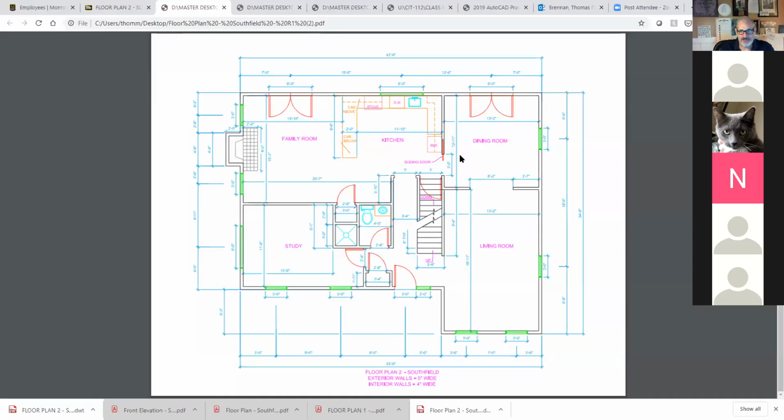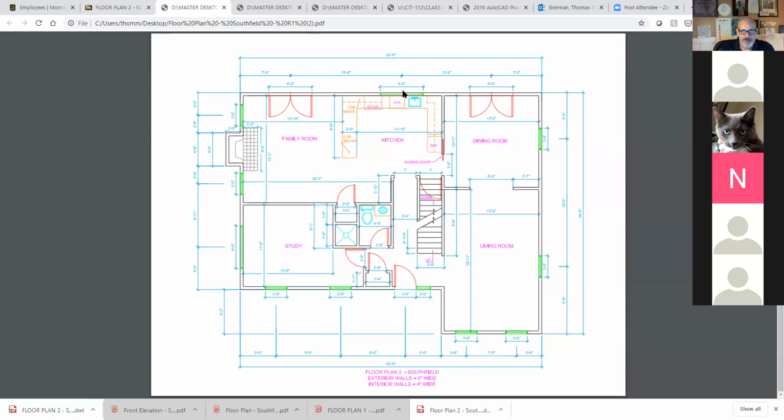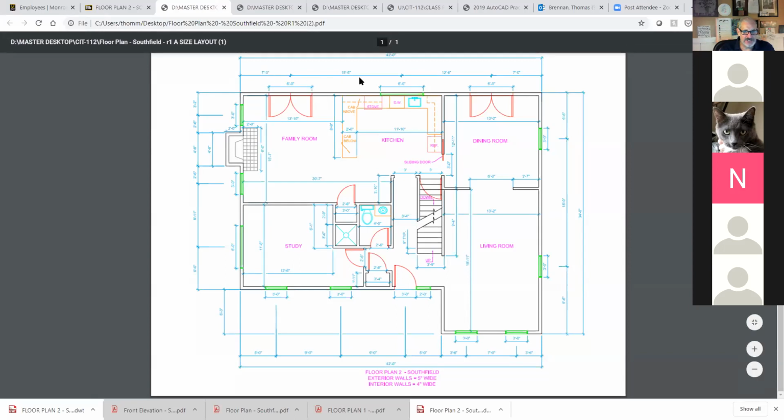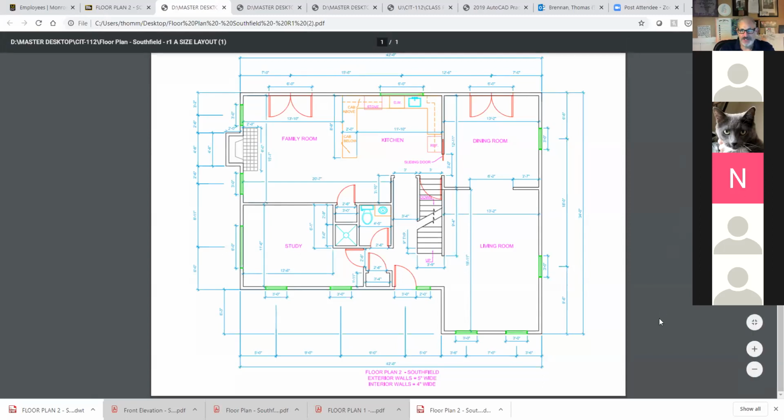So over here, what is the problem? And you guys should be able to see the floor plan one right now. It's right up here. I've got 3-foot windows. This is a 6-foot window. And the 6-foot window is located a distance of 7 feet plus 15 feet 6 to the center point. So 7 feet plus 15 foot 6 is 22 feet 6, okay? So it's 22 feet 6 from here. So that's where it's got to be centered, 22 feet 6. So remember that. I'm going to put it in place, and I'm going to show you how to fix it using properties. So this is kind of cool here.